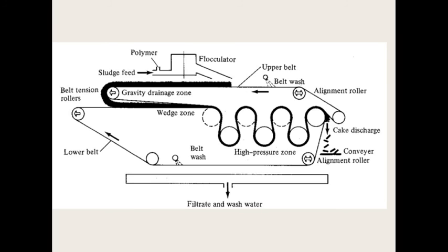So mostly these are the various ways to reuse digested or composted sludge in agriculture. It may also be sprayed on agricultural land to make use of its value as a soil conditioner and fertilizer. But since sludge may contain toxic industrial chemicals, it is not sprayed on land where crops are grown for human consumption.